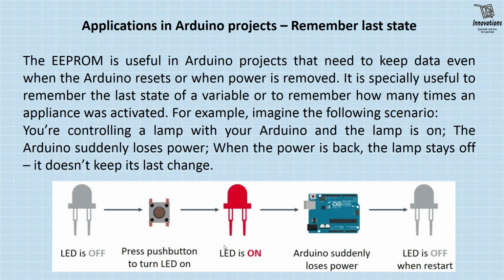So what is the application of an EEPROM? We will see the applications in Arduino projects to remember the last state. The EEPROM is useful in Arduino projects that need to keep data even when the Arduino resets or when the power is removed. It is especially useful to remember the last state of a variable or to remember how many times an appliance was activated.